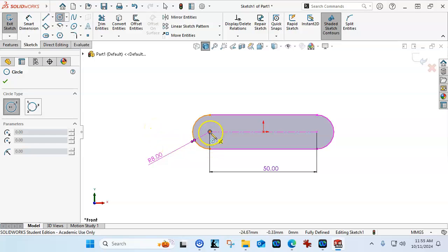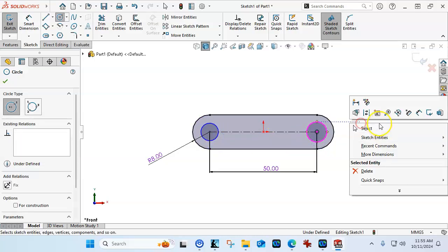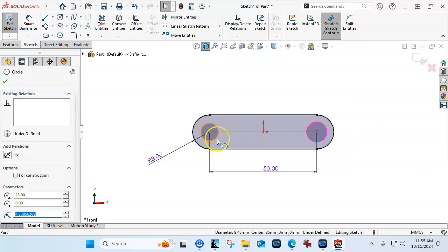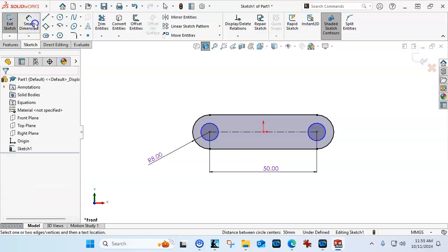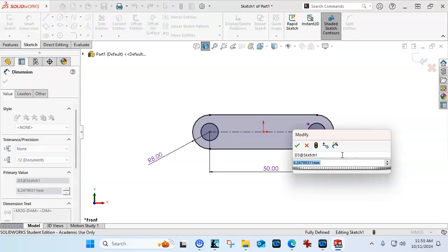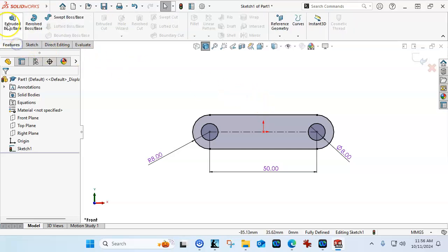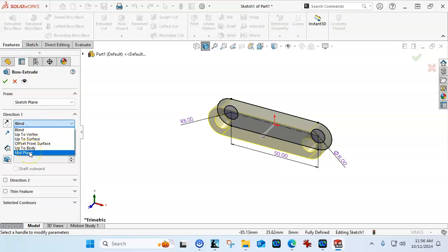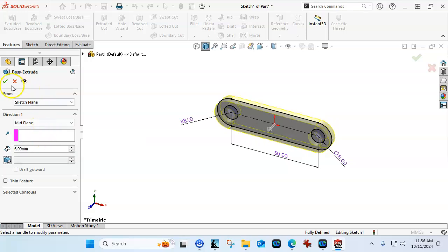And this is about the time when we want to start paying attention to our tolerances as well. So we'll make a pass after we do the drawing and think about what we would actually be putting through here for bolts and mounting to our geometry. So let's go ahead and make that equal. We'll add the smart dimension for an 8mm. And because I want this to be centered, when we go into the extrude, we're going to switch to midplane. And under midplane, we have a dimension of 6.